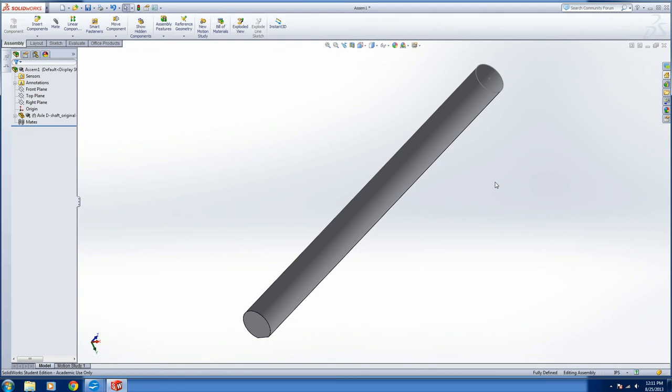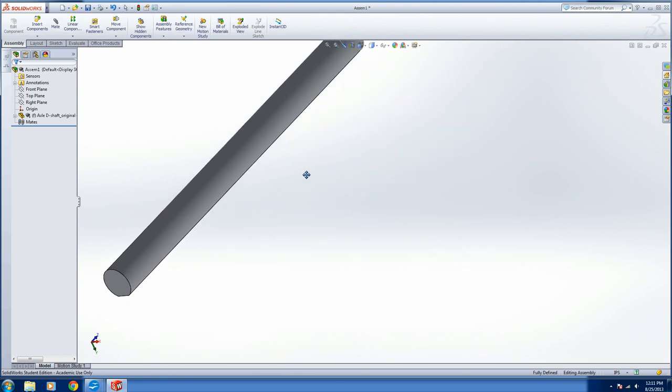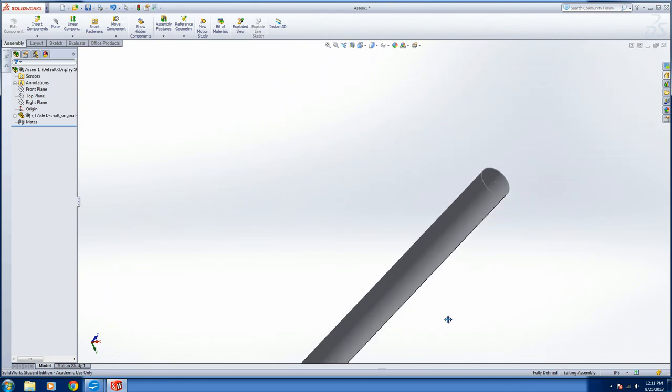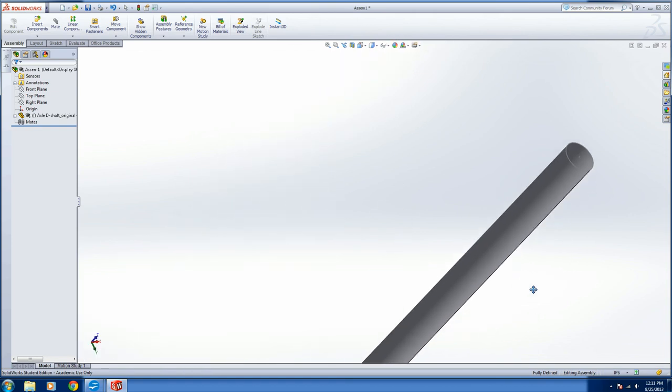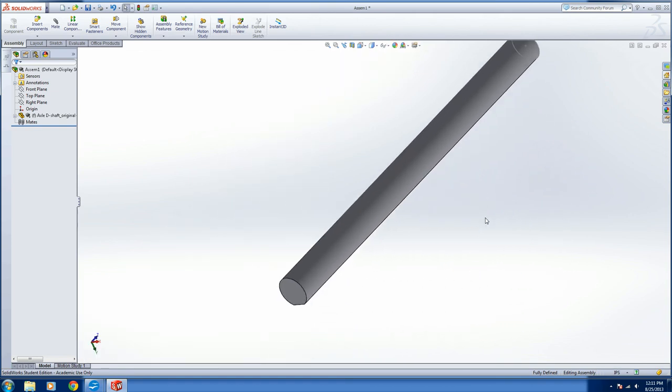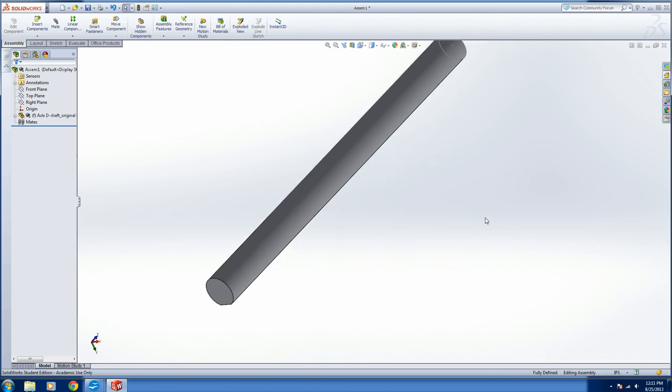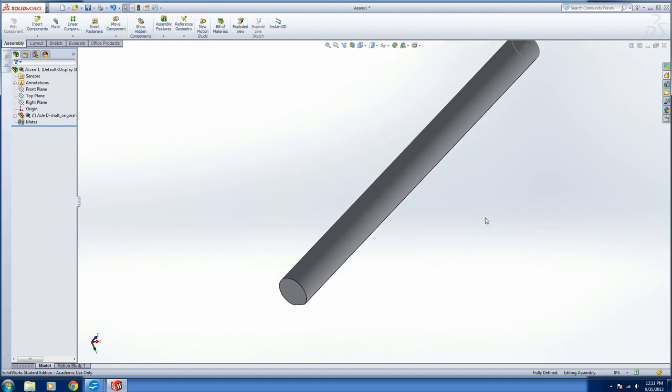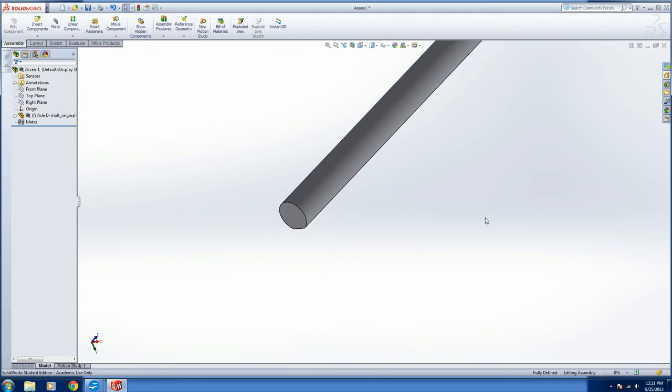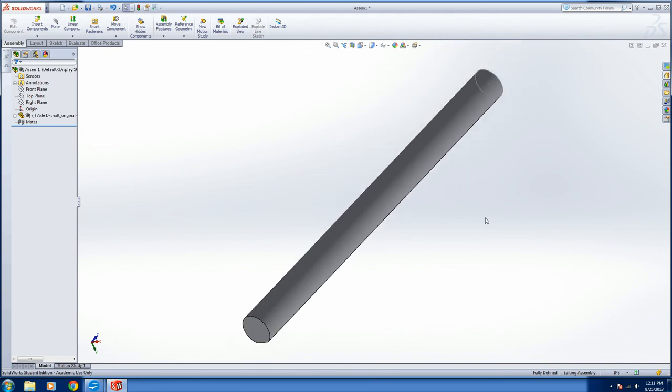I don't really use side to side. The scroll wheel for zoom in and out and rotating is generally enough for me. But if you do want to know, you hold down the control key and the middle mouse button and you can drag your view around. You can also use the arrow keys by holding down control. Your left is your right, your up is your down, and your down is your up. So that can be a little mind-boggling at first.